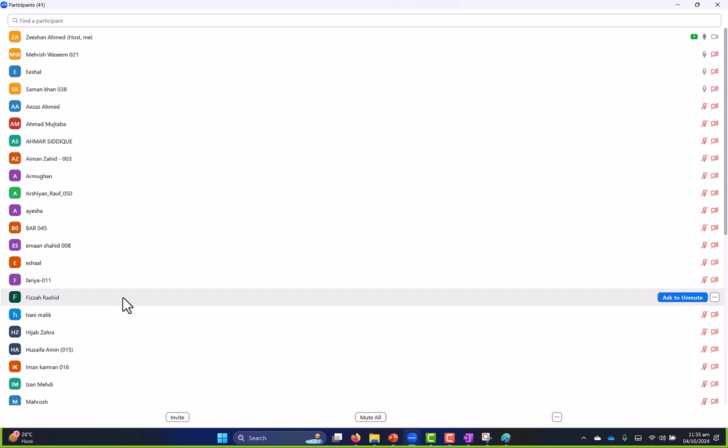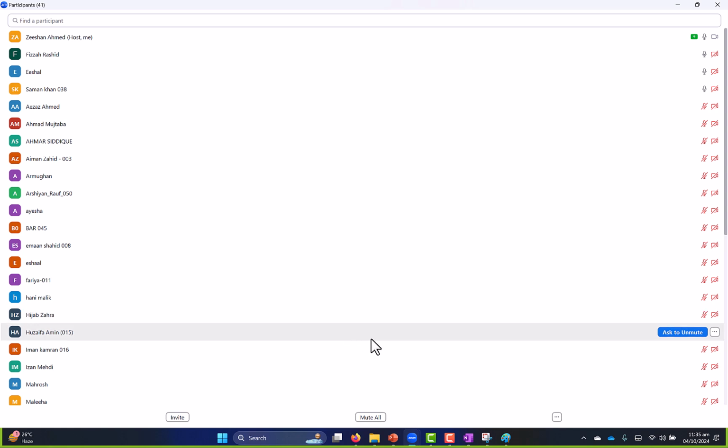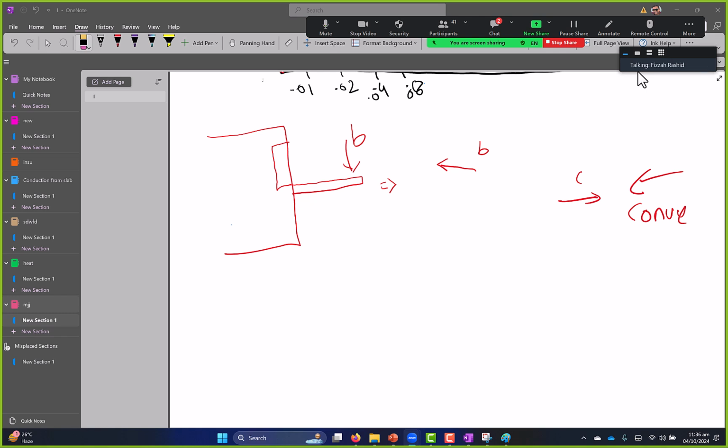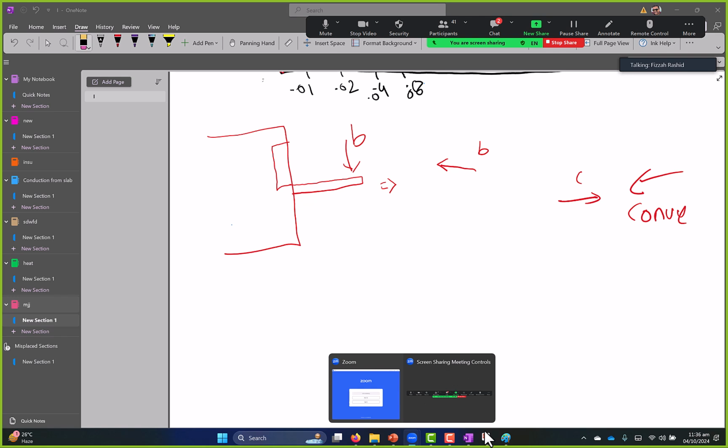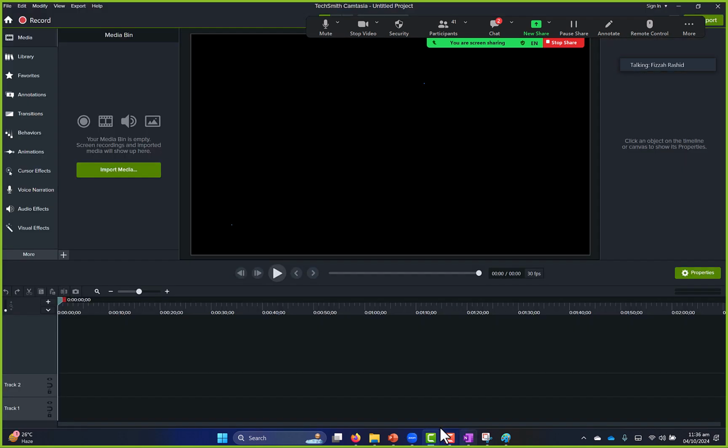That's why. Fiza, can you explain to me what just happened? What did I just say? Can you summarize it for me? Sir, you said tension will be on the upper side, so steel will be placed there because steel is good in tension and brick is good in compression, so steel for tension.